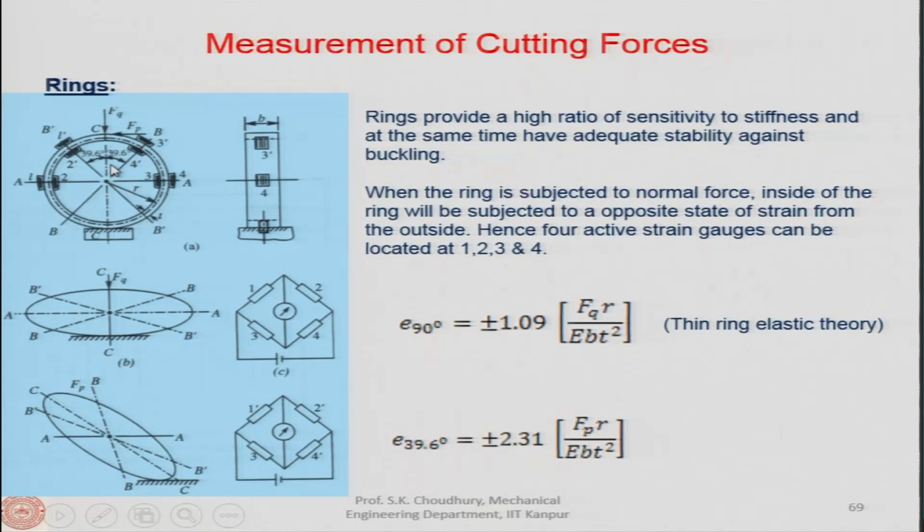This is not for all structures, this is particularly for the structure that we are talking about. This is a ring type structure, and these ring type structures go through photoelastic studies to find out what are the nodes where the maximum strain can occur. So, this is for the purpose of fixing or putting the sensor particularly in those positions.